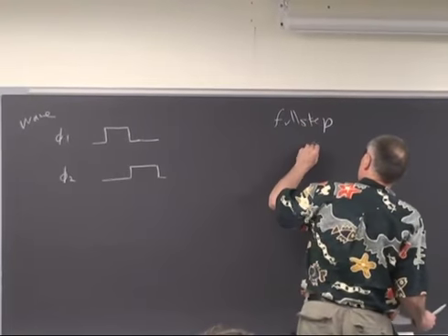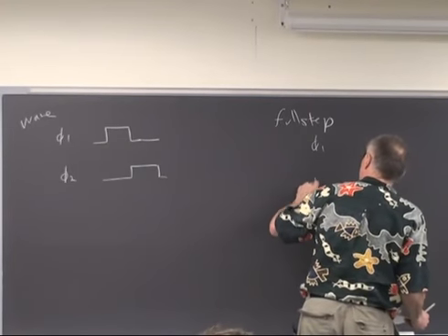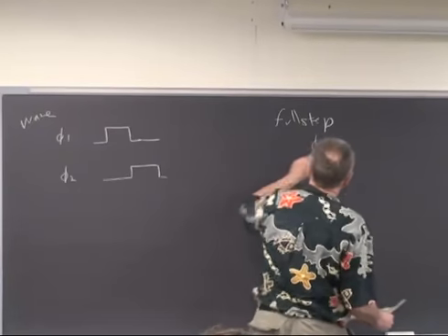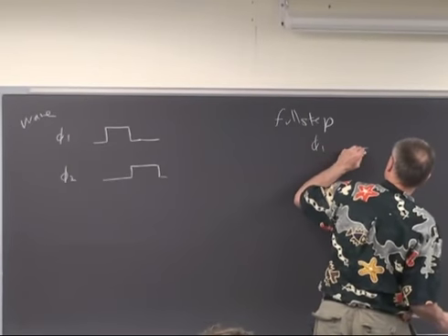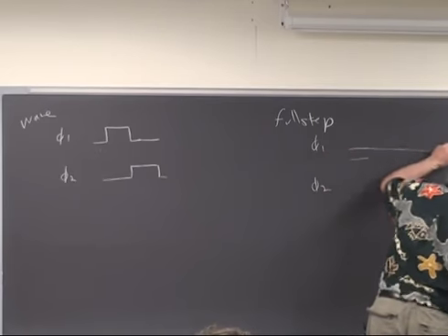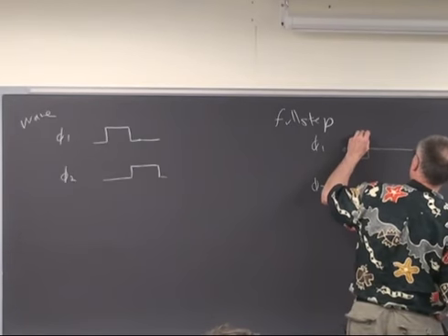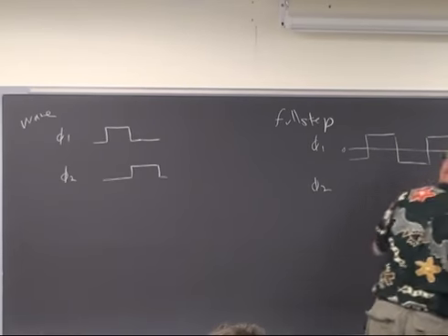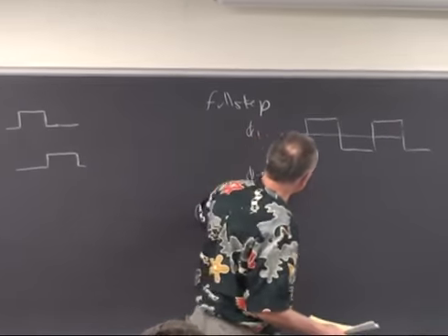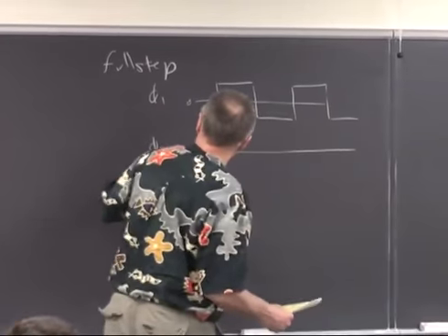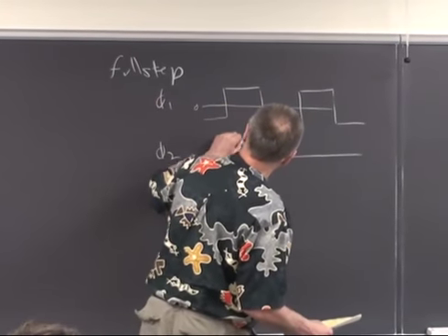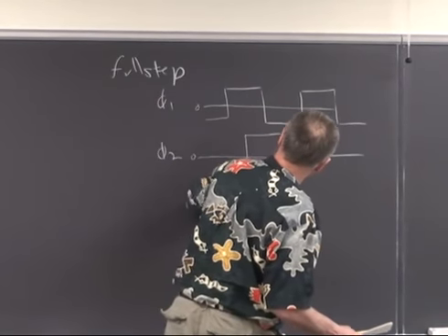And for a full step, phi 1 and phi 2 are going to look more like this. But I'll start this. So we're going to have 0 here, and we're going to step it positive and negative continuously, and phase 2 is going to be 90 degrees out of phase, looking like this.